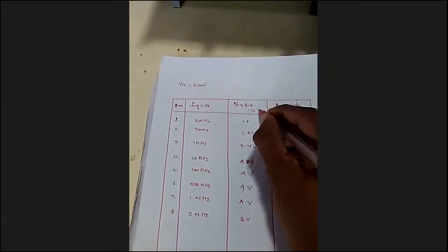So when I substitute this Vo and Vin, the gain is equal to 20 log Vo by Vin. Then I get these values: 32.97 for 1 volt, that is at 200 hertz, then 38.06, 41.58, 46.02 over a constant range, and then it changes.